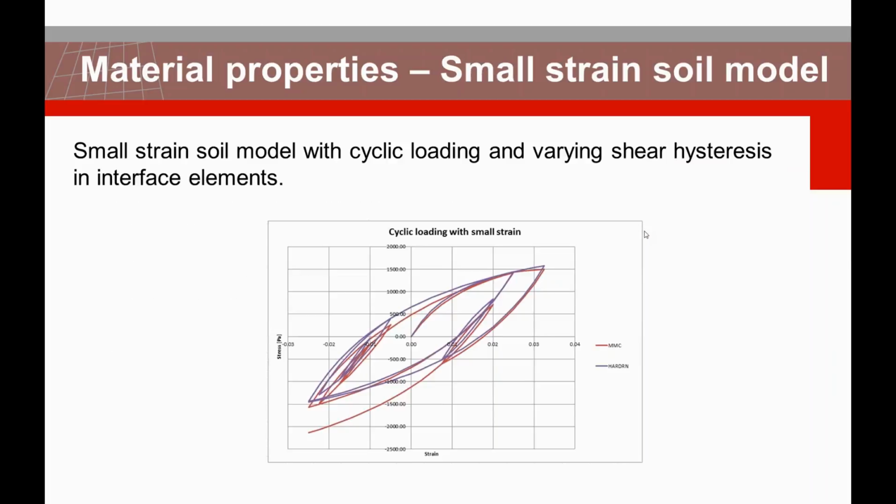Another extension and detailed development that we have is for the small strain soil model. This one is in conjunction with the modified Mohr-Coulomb, an extension of that with hardening, and that way you can capture the cyclic behavior of your model, hysteretic behavior, and also we incorporate that with our interface element.